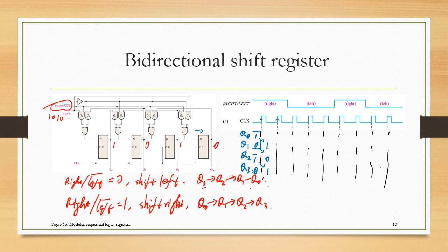So we will shift again, and this will shift out, so it is no longer stored in here. But what happens to those? This will be 0 actually. Basically, it's because after the real data is stored, we just reset the data input to be 0. So all the new data will be 0. That's why we got 0 at those locations. Now at the next edge, it's shift left, right? Shift left, which means go up. So this 0 will be here.